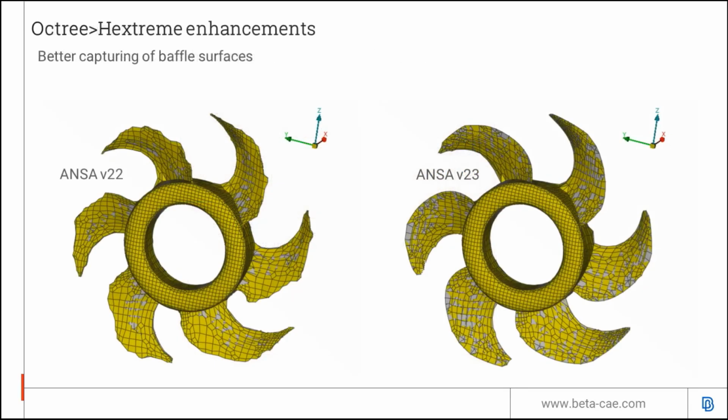Moving on to extreme meshing, there's been a lot of improvement with respect to capturing zero thickness walls, baffle areas. In the past, this was not so well maintained. Now, the detection and capturing of zero thickness walls is more accurate.